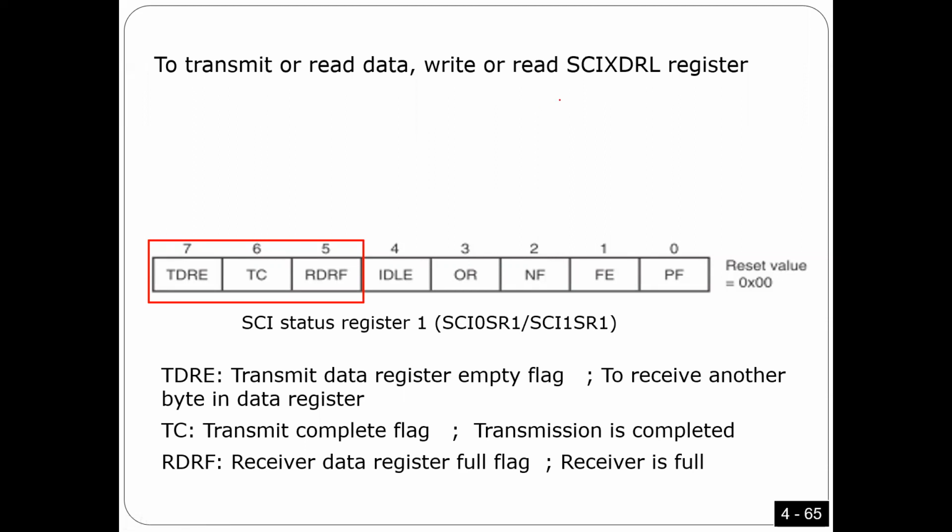Okay, for example, I'm going to tell you what the idea is. The idea is that we have a register here, guys. This register is called SCIx. What does x mean? x can be 0 or 1, as I told you before, because we have two, one for serial communication 0 and 1. Again, we're going to use 1 all the time because 0 is going to be used by CodeWarrior. Anyway, I just want to tell you how easy it is.